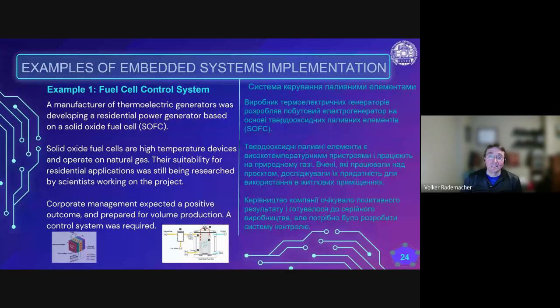Most of the time these are used to power telemetry equipment on gas pipelines, because there is natural gas or propane available, and there is equipment, radio equipment for example, or satellite equipment, measurement equipment that needs to be powered but doesn't need much power. These thermoelectric generators are ideal for that. Again, terrible efficiency, but exceptional robustness.